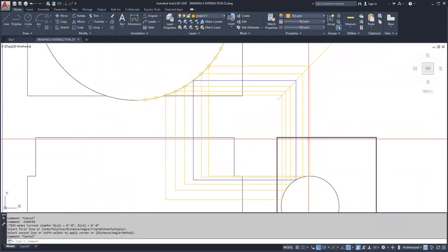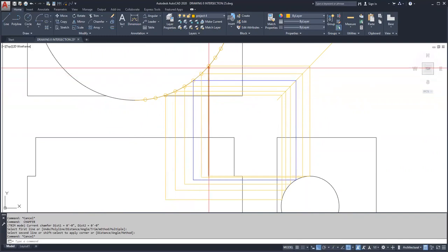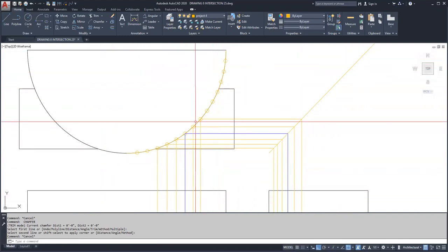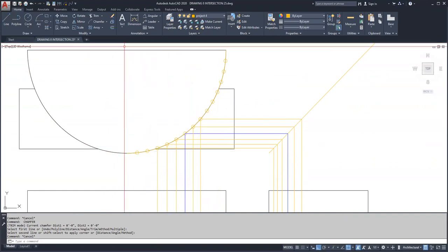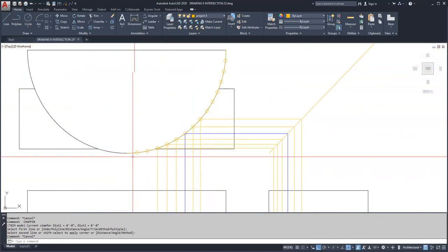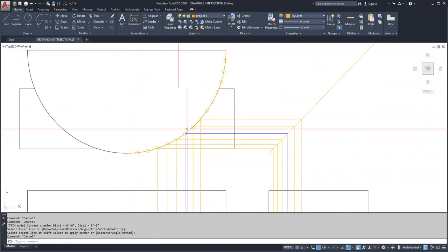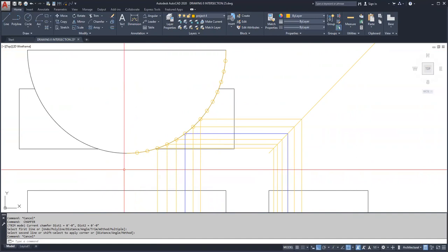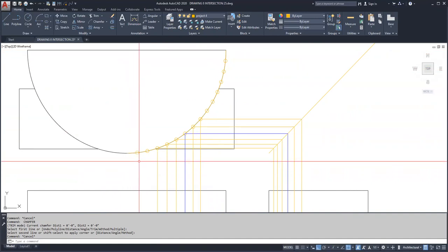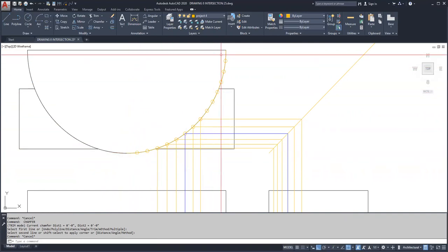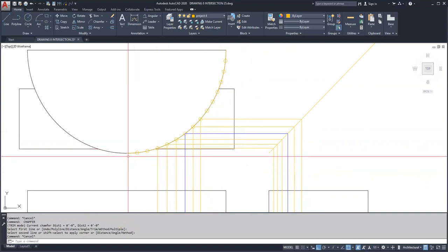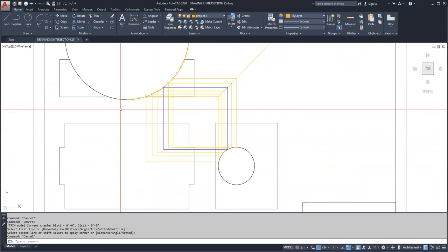All right. So you're really just going to get 1, 2, 3, 4, 5, 6. Now, I broke it up into 15 parts, which came out to 6 degrees. So you can use your compass here to project the 6 degrees and break it up, or put your protractor and project the points, or use your dividers. However, actually the more points the merrier, so it's up to you how many points you want. But I would say that's a good number.